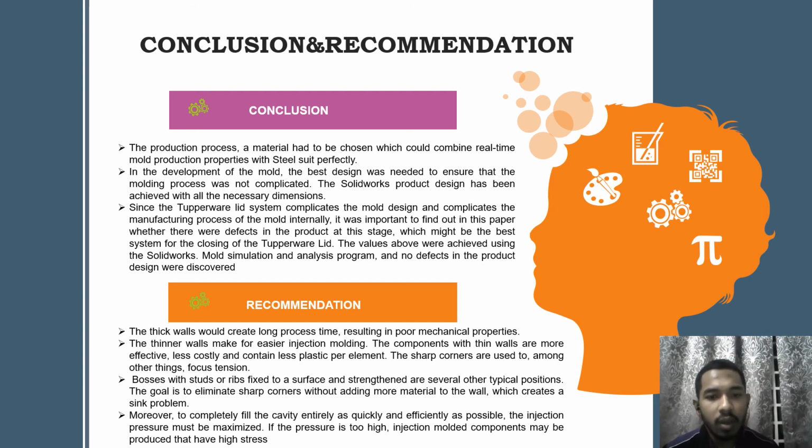The values above were achieved using the SolidWorks mold simulation and analysis program, and no defects in the product design were discovered. Recommendation. The thick walls would create long process time, resulting in poor mechanical properties. The thinner walls make for easier injection molding. Components with thin walls are more effective, less costly, and contain less plastic per element.